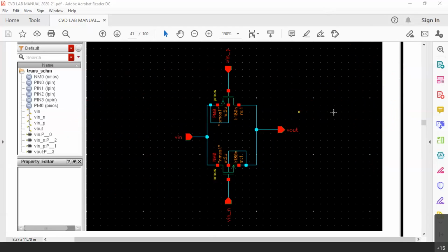But in the case of transmission gate, there is no power dissipation at all. Means, in this circuitry, you will not see any power supply at all. It is the recombination of input signals itself in many different ways. We are going to implement the logic circuits. That's why I had told you that you can take up a mini project in the next semester to implement a full adder only using transmission gates, without using regular CMOS circuitry at all. Only using transmission gates. It is possible, people have worked on it.